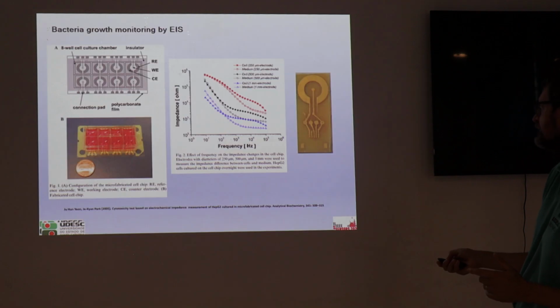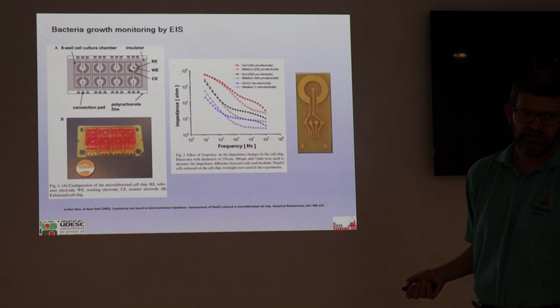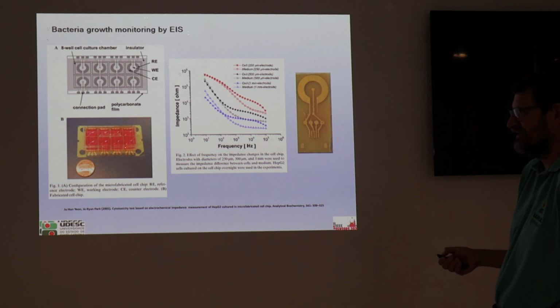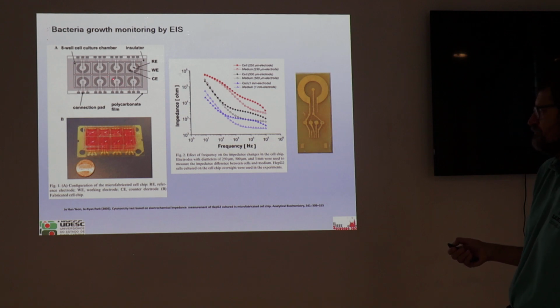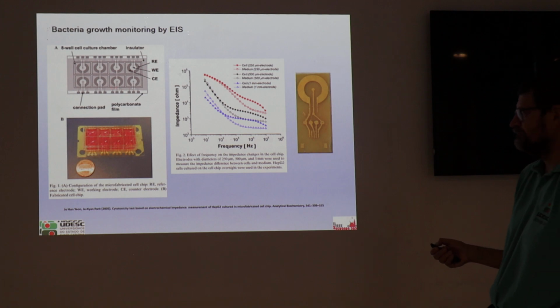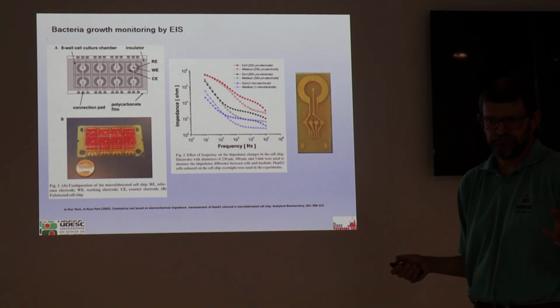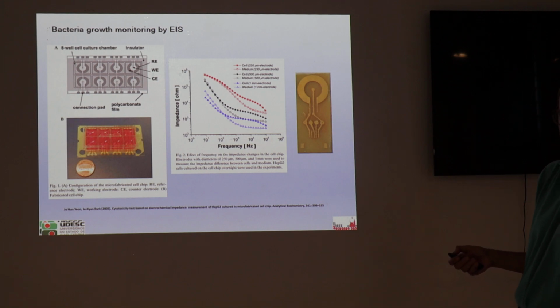Okay, and that's the work that we have been doing here in UDESC, in our lab. We've been doing this type of electronics setup, building, printing this with gold. We have been using this sputtering technique to vaporize gold on the metal here.